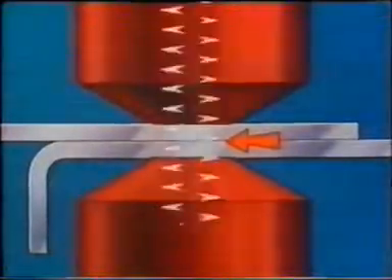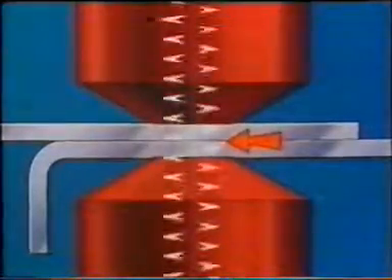The current then flows easily out through the second electrode. In the confined area of high resistance at the interface, heat is generated which raises the steel to its plastic temperature. The current is switched off, but the pressure is maintained while the metal cools to form a weld nugget which joins the sheets together with a strength equal to the parent metals.